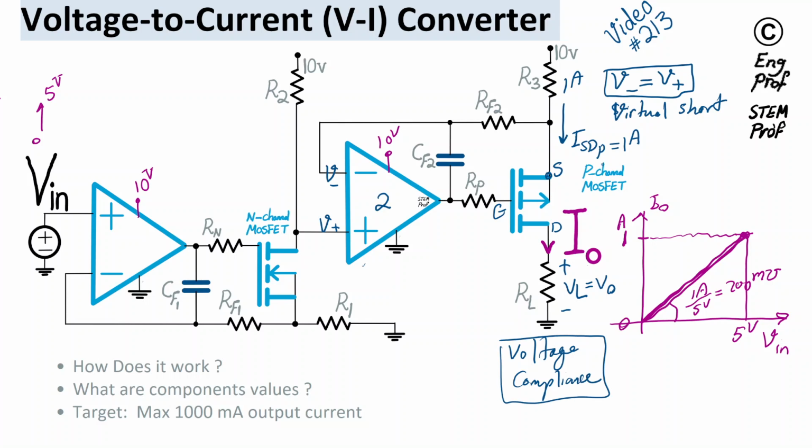Let's say if the saturation voltage V_DS sat of the PMOS is, for example, 0.5 to 1 volt for power PMOS, and something on the order of 0.5 volt to 1 volt is max tolerable for the voltage drop across R3. So as an example, let's shoot for just 1 volt drop across R3 max. I'm going to write it here: VR3 max is going to be 1 volt.